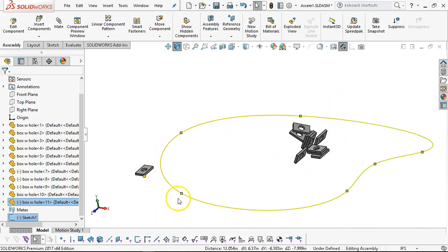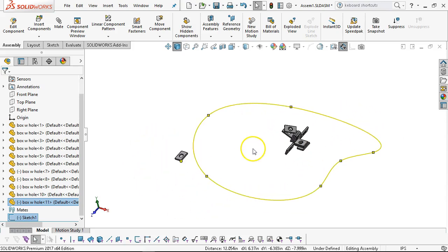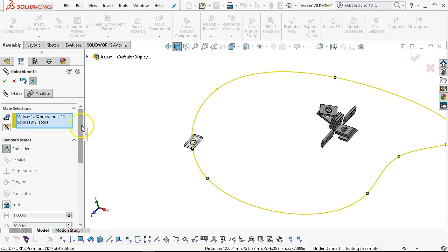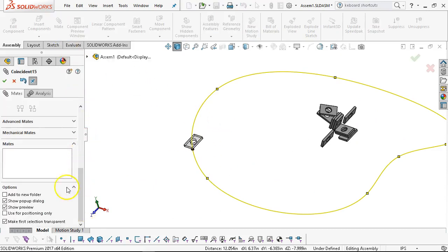If I'd drawn arcs and fillets and lines, whenever it found one of those endpoints, it would have said, okay, path, you're done. All right, so converting over to a spline, or fitting a spline, generating the spline gives you a continuous path. All right, so we went continuous.